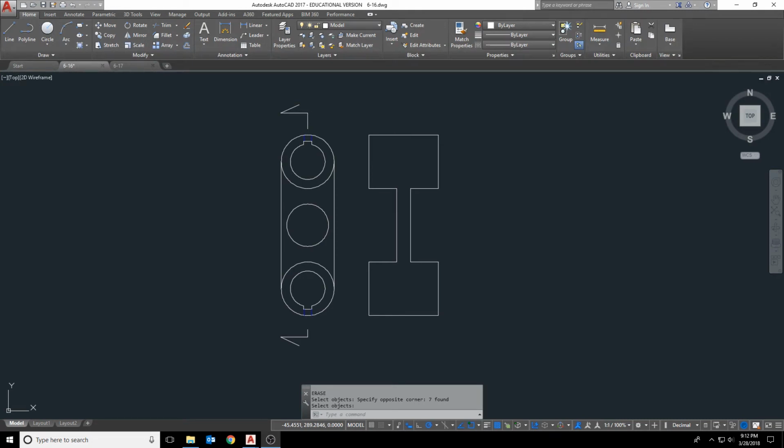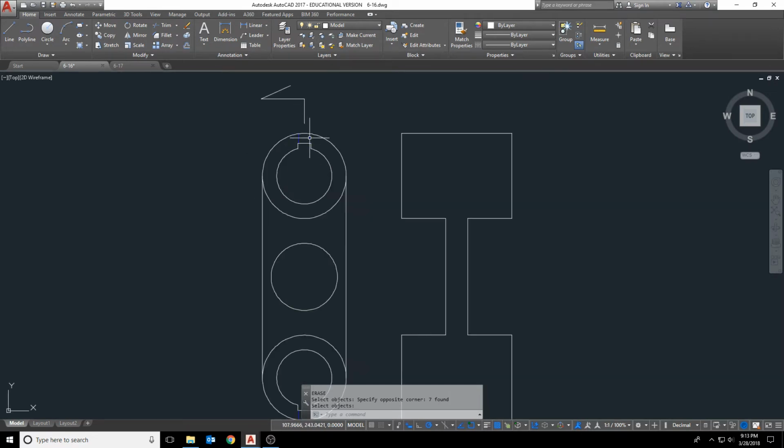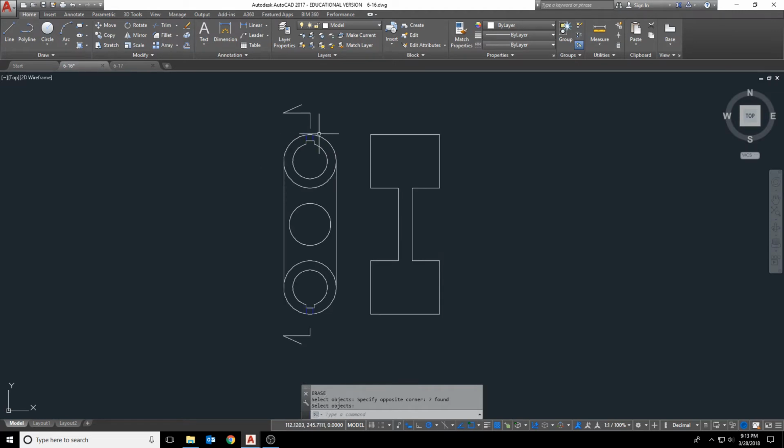In exercise 6-16, I've already drawn the top view and the profile of the section view, which is no different than drawing, say, the right side view. I've also put in my section lines, and I've got hidden lines in my top view to represent the small holes. So don't forget about those holes. It's called out as diameter 5, 2 places, second hole at other end of object in exercise 6-16.